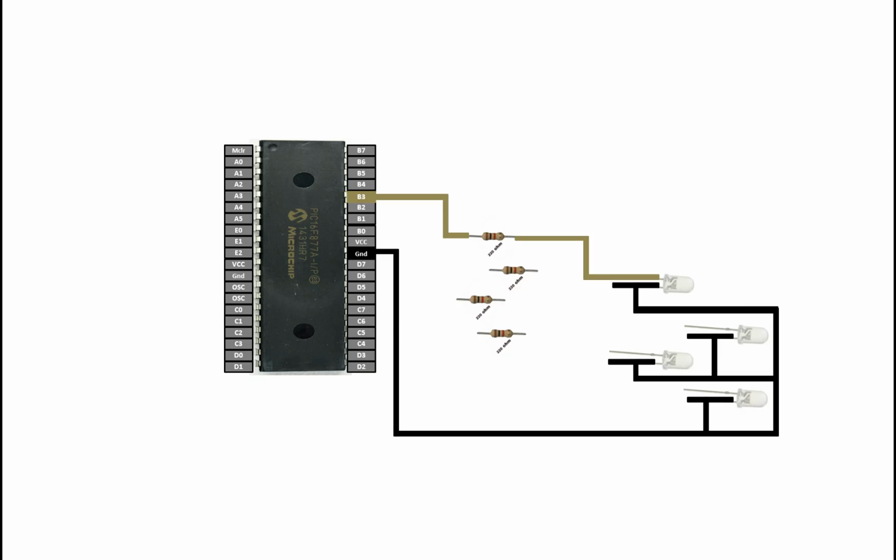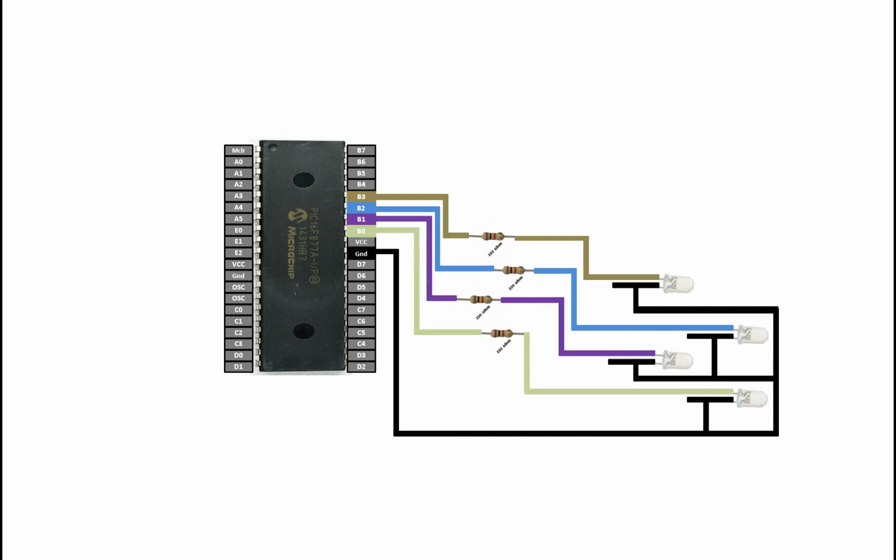of the forever loop. Now for the second LED, do the same, longer pin to the one end of the 220 ohm resistor. From the other end, connect it to any available digital input output pin like this. For the third LED, do the same. I'm going to use a pin of B1. For the fourth LED, I'm going to use a pin number B0 like this. Now for the button which will initiate the break statement, as soon as it is pressed,